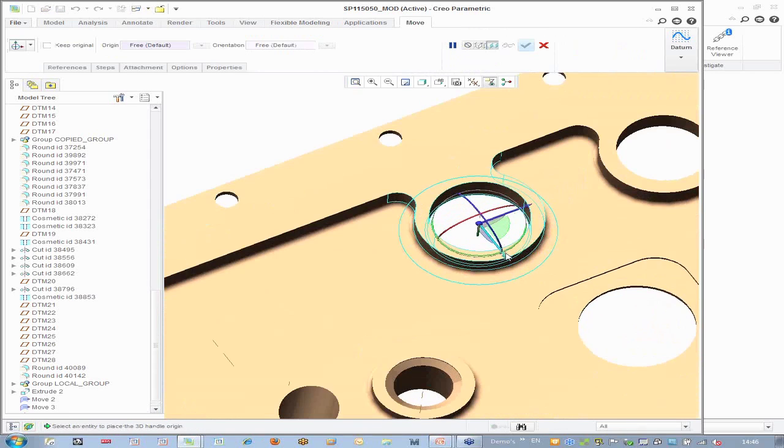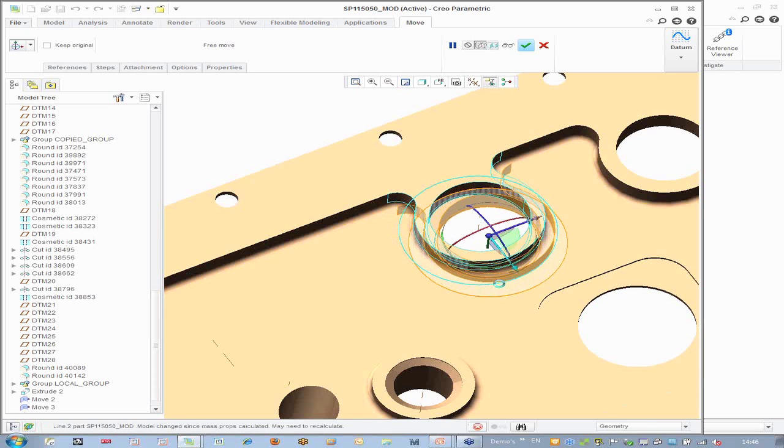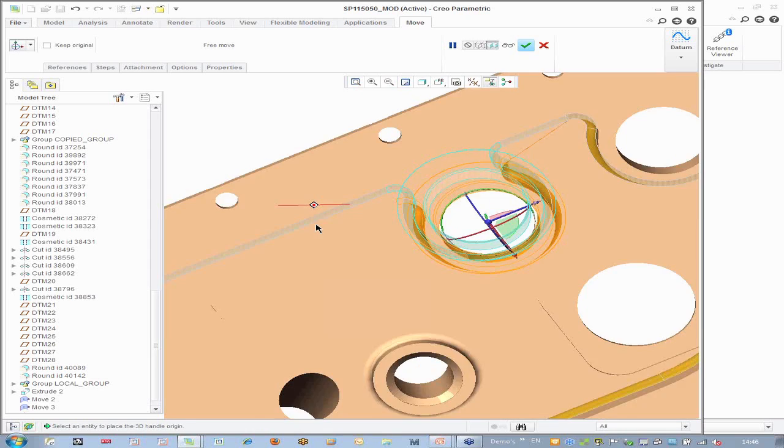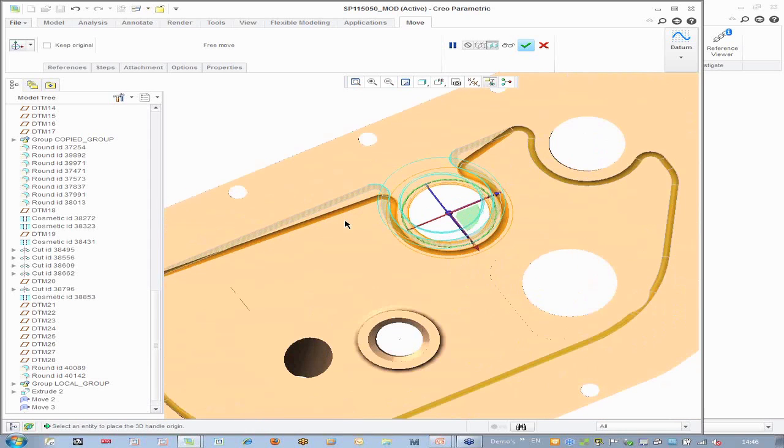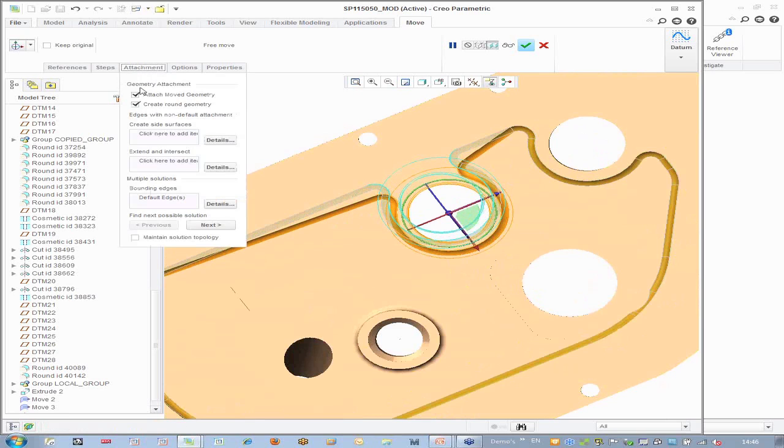Now, as I start to pull this out, I would hope, as you would expect, we'll pull these surfaces out, but this surface will change because of the attaching surface. So as I pull it out, everything updates. Now, clearly that's not really what I want, because I'd like these to be nice and straight, because that makes my manufacturing much cheaper. So I can change the way in which it maybe attaches.